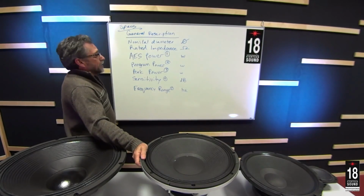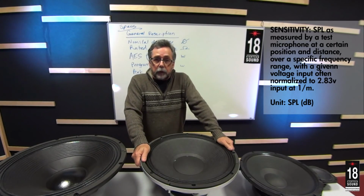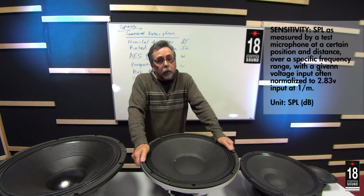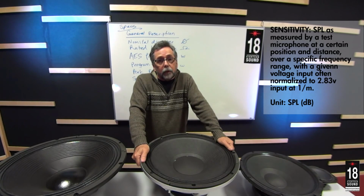Following, we have sensitivity, also with the footnote. The sensitivity will tell you how loud the speaker will play in dB at a certain position, a distance, and preferably over a frequency range or a specific frequency. Again, the footnote's important to understand how sensitivity is defined. We will typically define sensitivity over a bandwidth with a given voltage input.